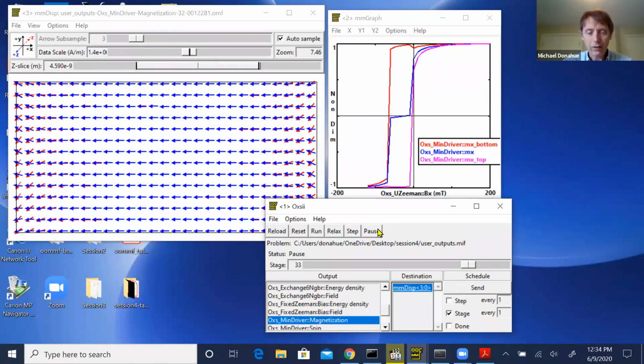If you're running at really low damping, damping of course helps dampen out numerical errors as well as other sources of perturbation in the system. If you have really low damping, then that can sort of build up. And I think Don and I wrote a paper on this. It turns out there's another method in there, RK4, your standard fourth order Runge-Kutta.